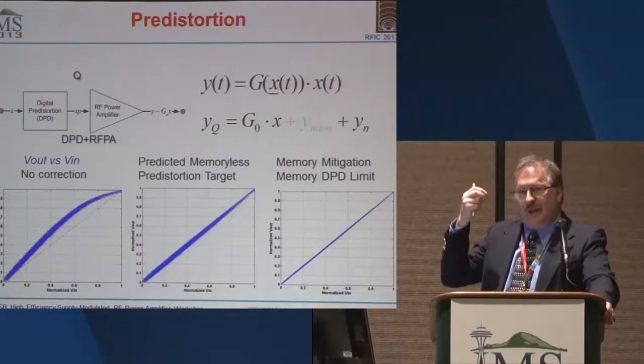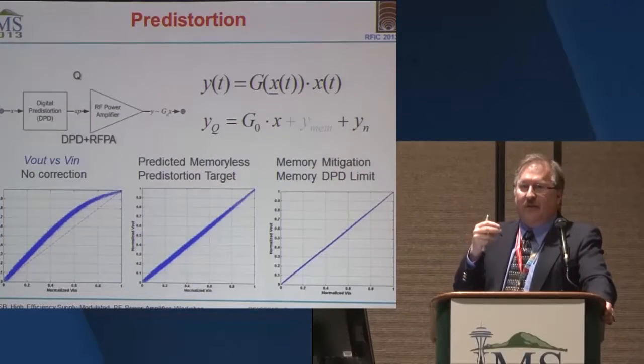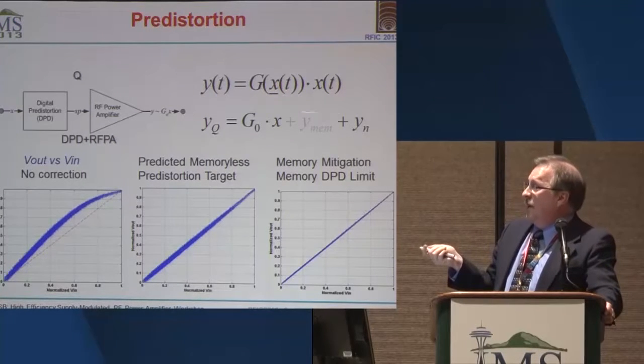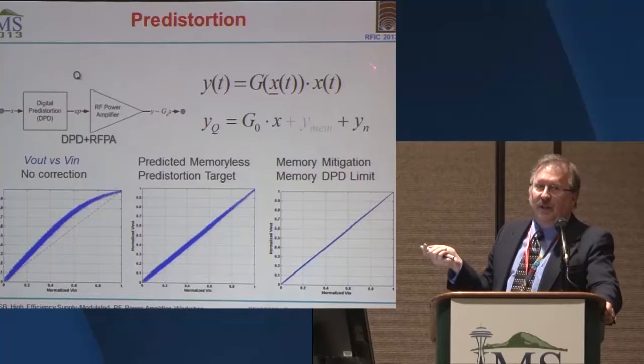And in the same way we do averaging with the spectrum analyzer, I can use that repeated sequence and do averaging on it, and take each capture as an entry in an ensemble. And when I do that, I can identify changes that are deterministic to each sample point in the sequence. And again, it's the exact same thing as all the other averaging we do in so many other measurements. And in that way, I'm able to eliminate the deterministic memory.